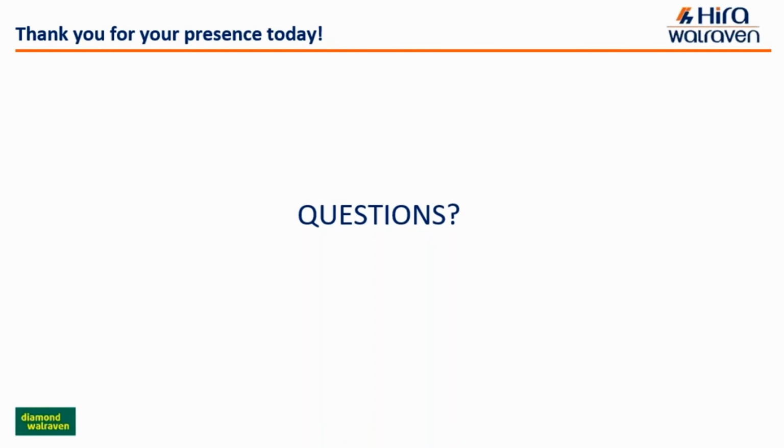From Mohammed Parvez Alam, the question is that most of the time data is not available. In that case, is there any thumb rule to calculate seismic force? Yes, there is. If you don't have enough data, then seismic design category D needs to be considered, as per ASCE. But if you have some clue, at least what soil profile type it is, or based on the region of your project, we can recommend the seismic force factor that should be applied for your system.